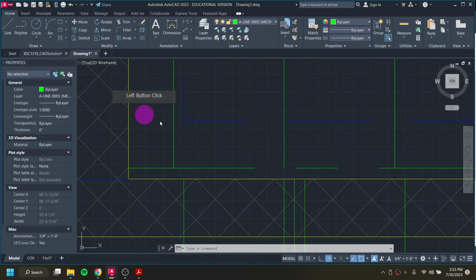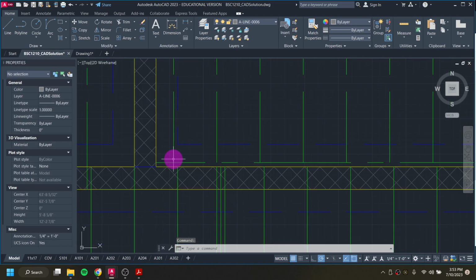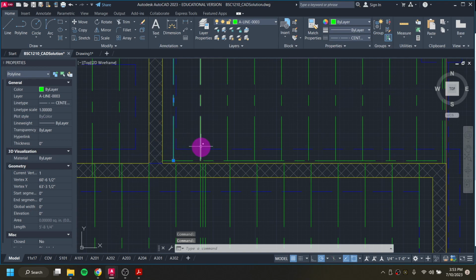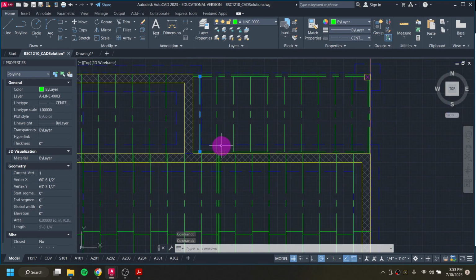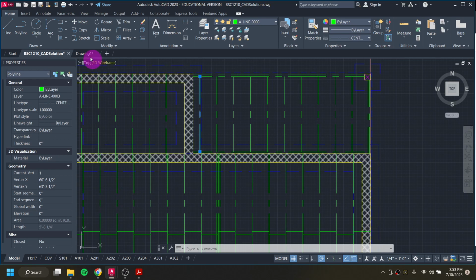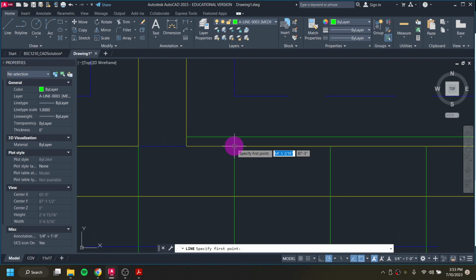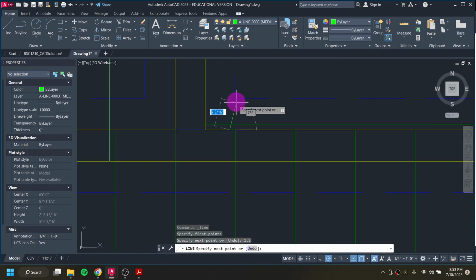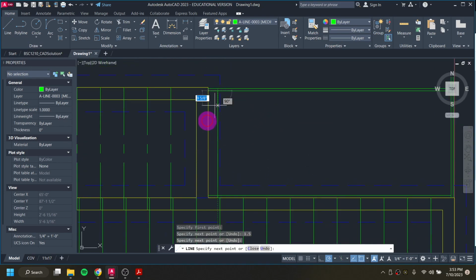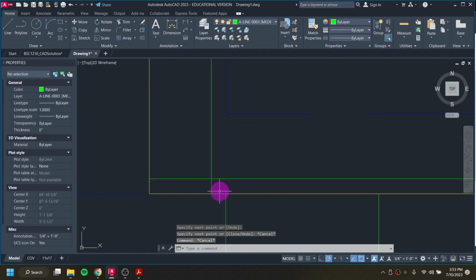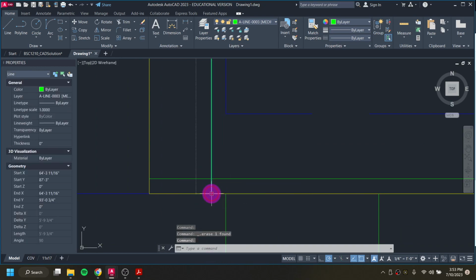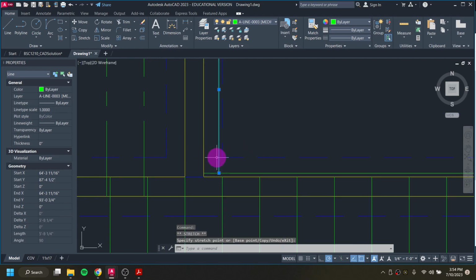And then we have these joists spanning across. So it's 1.5 over. We'll have this first one, and then we can just use the offset tool to keep them going across. So line from this joist 1.5 over, and I'll go straight up until I meet where that band is. Escape to end the tool. Click on that little guy, delete it. Click on this one, and I'm going to stretch its grip up so that it's the correct length.